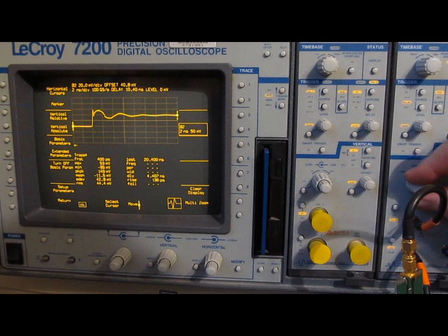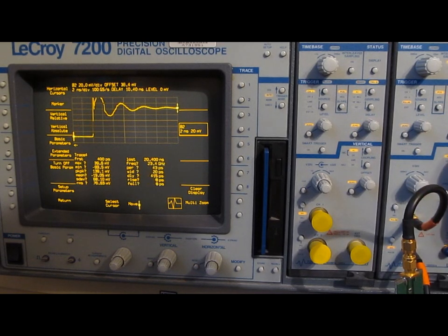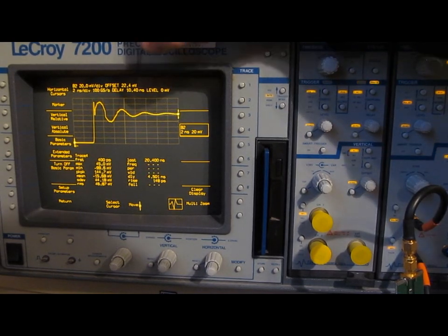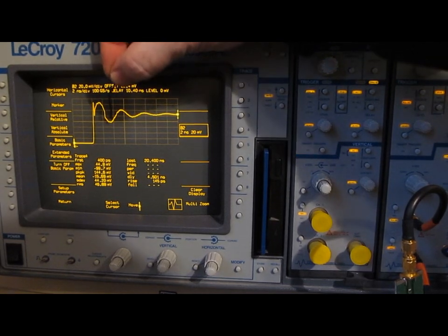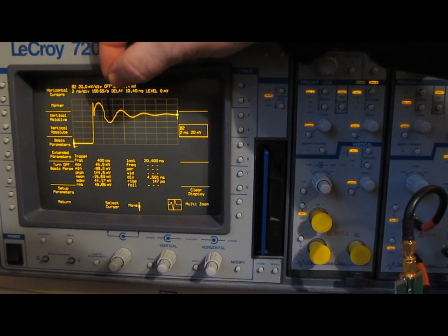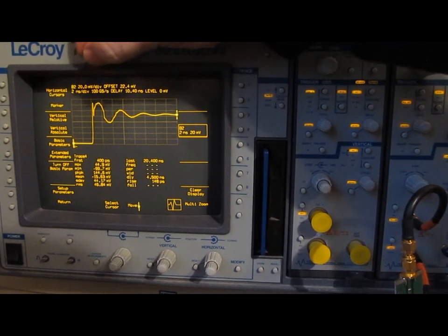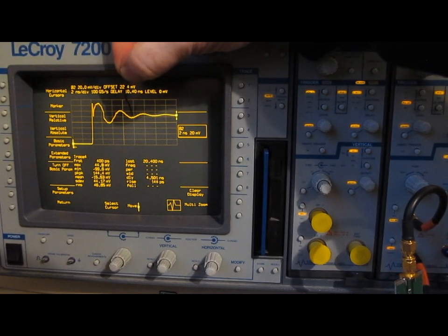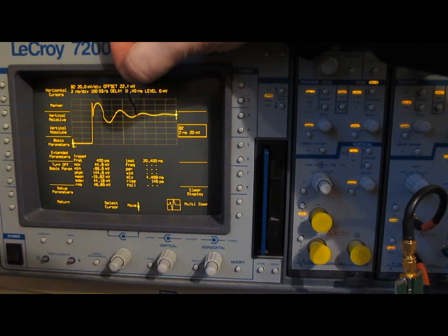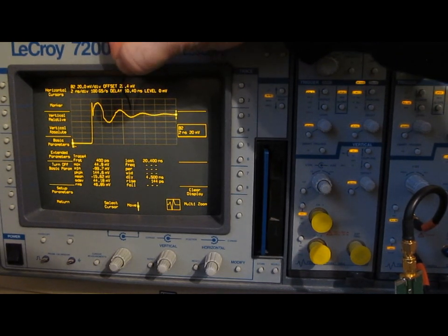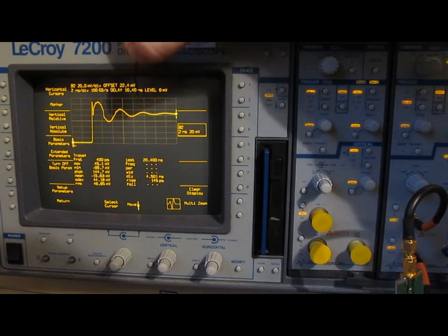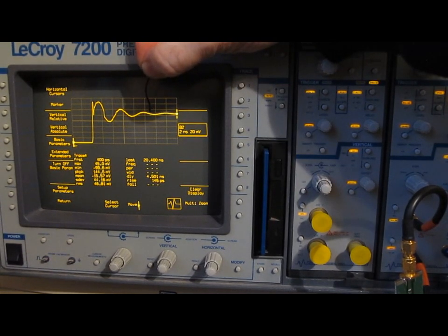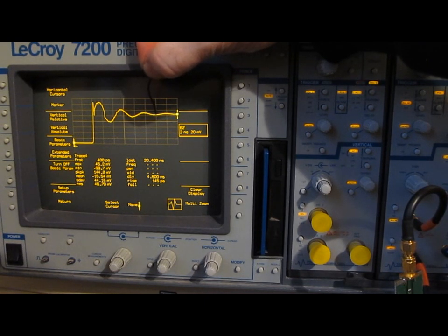Let's go ahead and we'll zoom into this vertically a little bit. Bring our offset down. And it looks like our peak is indeed roughly 30% higher. Notice our first valley here is basically 1.5 divisions over, and we're currently at 2 nanoseconds per division, or 3 nanoseconds out. Here's our second dip, which is 1, 2, 3, 4 divisions out. So just shy of 4 divisions, or yeah, probably roughly 7 nanoseconds. And right here you can just see our third valley, and again that's 8 divisions out, or just shy of 12 nanoseconds.